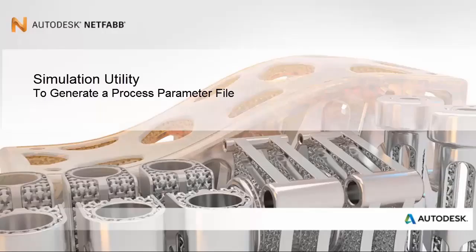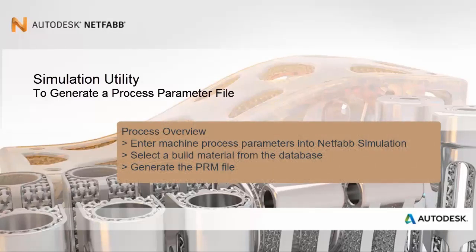An overview of the process of PRM file generation is as follows. Enter the machine process parameters into NETFABB simulation, select a build material from the database, and then generate the PRM file.